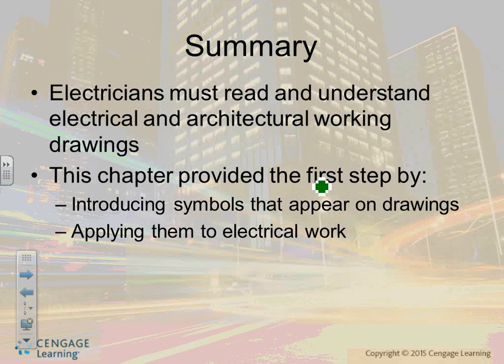If you have a dashed line with a U on it, what do you guys think that would be? Underground feeder. If you have a UT, underground telephone, UFA, underground fire alarm. If you have UTV, TV. If you have that symbol with MH, manhole, handhole. You guys familiar with manhole? Manhole, a man can get in. Handhole, only your hand can get in. Conduit, prefabrication, manholes, and what's not. So these are the symbols that you use.